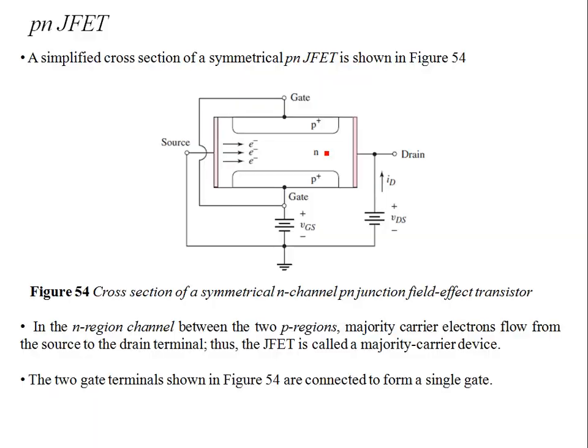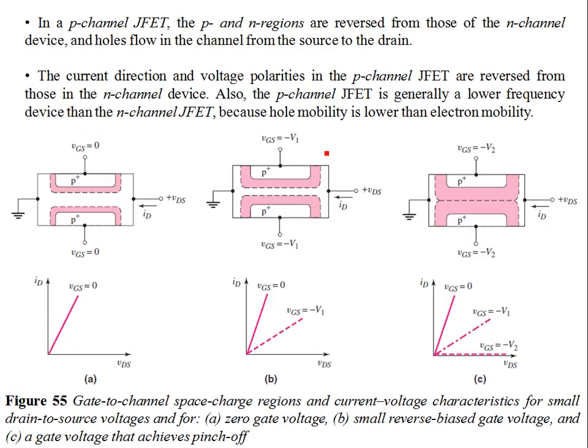Now, if you recall the construction we talked about earlier, you have an N channel device over here, right? The electrons are flowing from source to drain. So this is open circuit conditions. In these conditions, ID is your IDSS. For a small application of VDS, you have a small current IDSS, and this is generally in the ohmic region or linear region of the ID VDS curve.